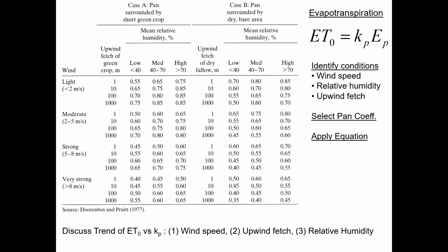That would be the amount of moisture that you'd have to replenish through irrigation, or by hoping for rain, in order to ensure that there's an equilibrium between the inflow of water to the crop and the outflow through evaporation and transpiration. So there are numerical models that help to estimate evaporation, and we have direct physical measurements with these pans. It's an important process that we have to be able to